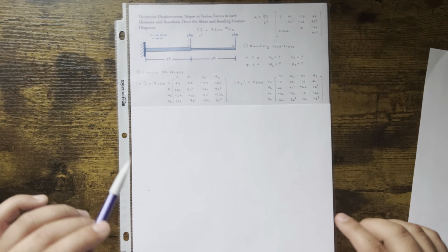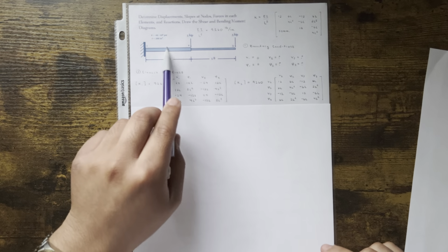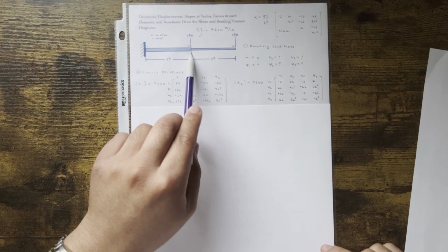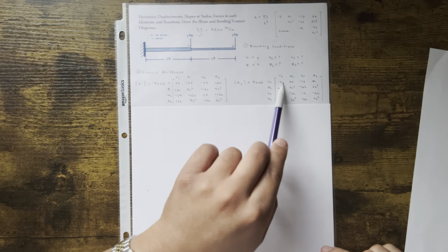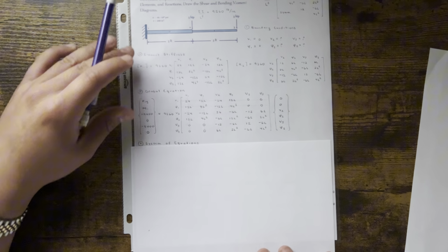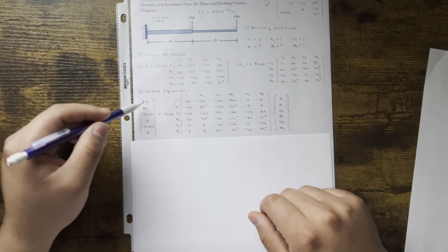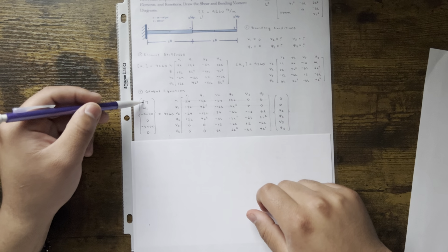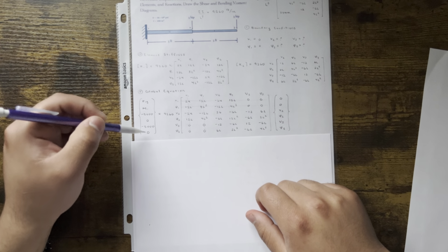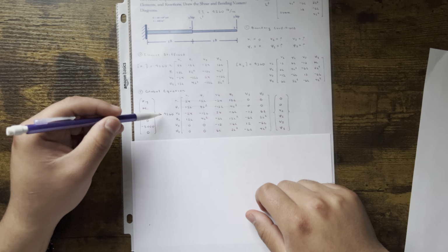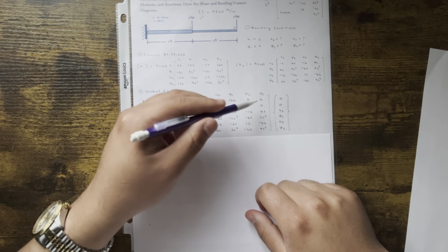So once you have that, you're able to add them, okay? The only ones that are going to overlap are V2 and Phi2 because both elements share the same node, which is node 2, okay? So these 4 are going to get added to these 4 right here. That's exactly what we did right here. We assembled the global equation, right? So it's just forces equal to Kx. So F1y, M1, F2y, M2, F3y, M3 is equal to 9260 times your global stiffness matrix.